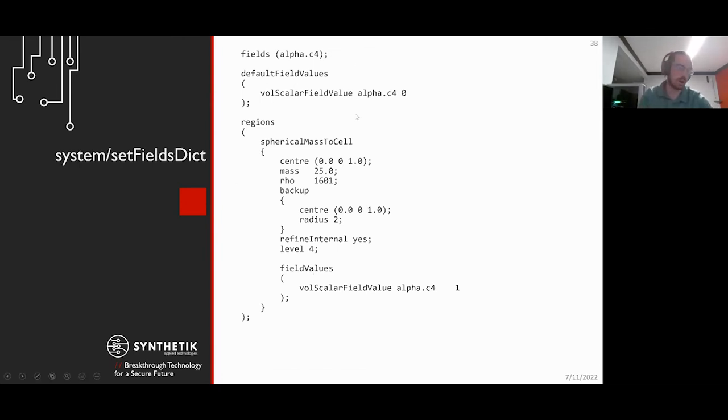In addition, we also have some other options. So rather than just the volScalarFieldValue, you also have some things like initialValue, which will keep any old non-uniform fields which are read in. Sum, which is nice for volume fractions, you can do 1 minus the sum of fields. massIntegrated. Function, which is, you can use function3, which are in blastFoam. Again, really just variations of function and function2.